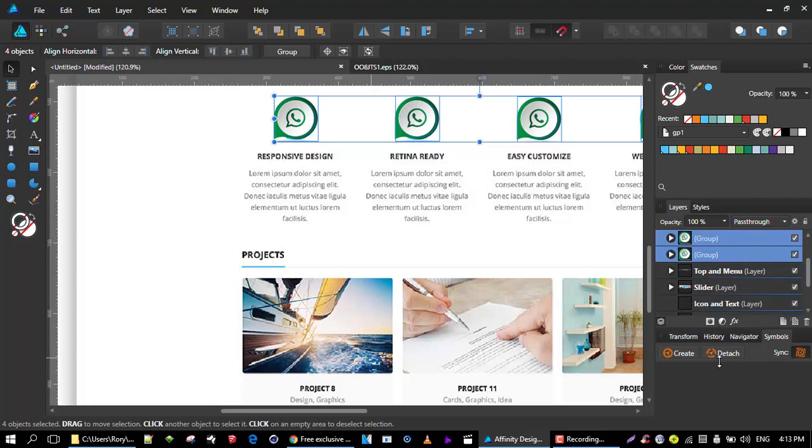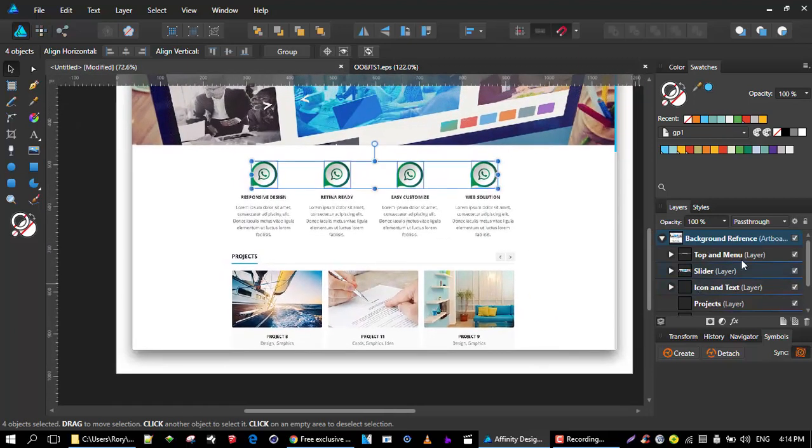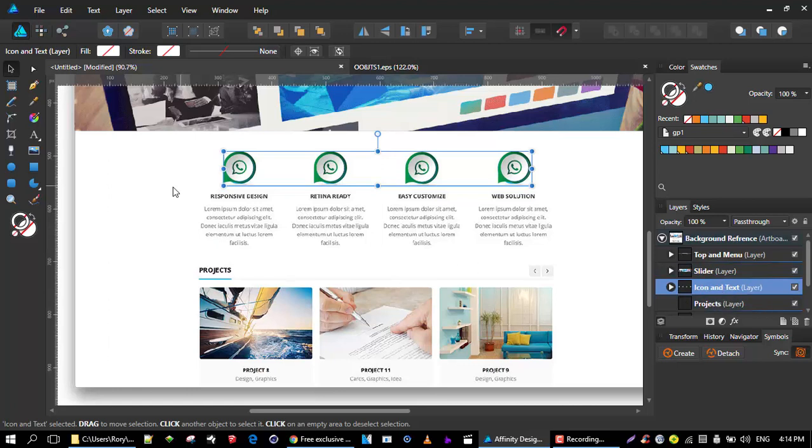See, it's always important to keep an eye on where these things are. Have we popped it into there? Yep. If I switch this layer off, icon and text, it should take it away. So it's important to occasionally look at the layers so that you don't mistakenly put things into other layers and then have issues finding stuff later. So I'm on the icon text layer.